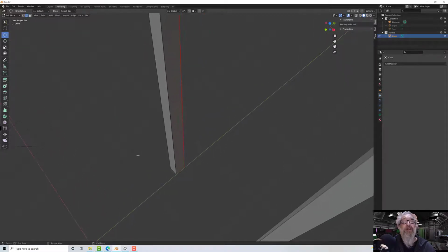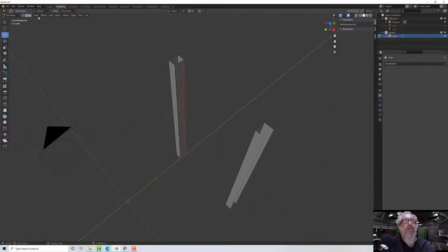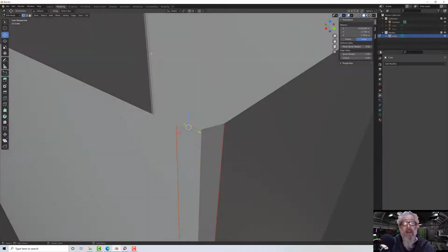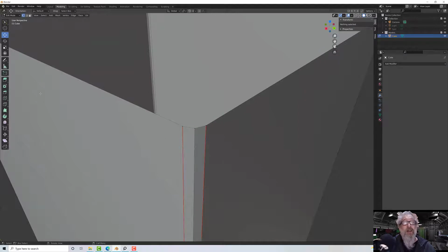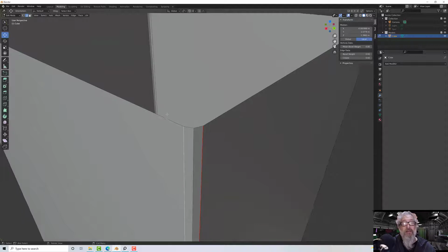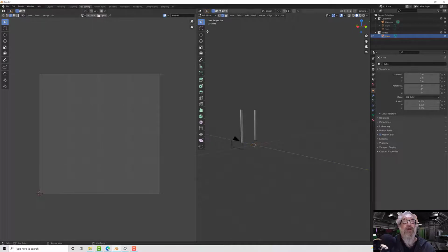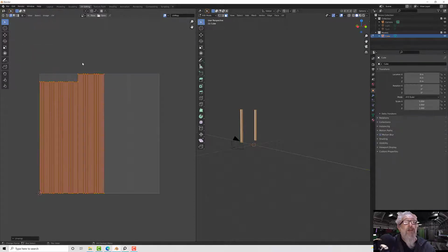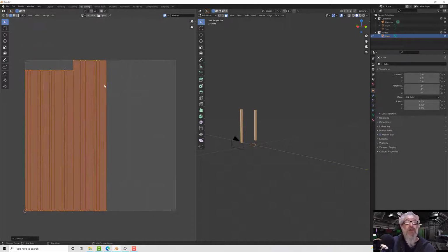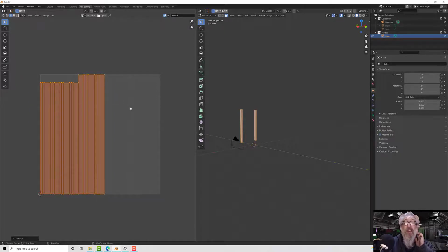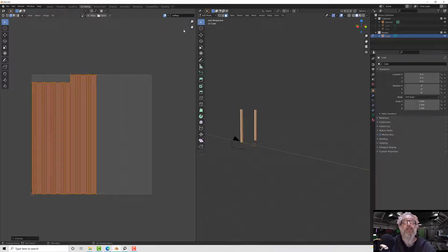Let's make sure that seam hasn't split into multiples. So it has. Okay, so I only need one of those as a seam, so I'm going to select that one, right click and clear seam. There we go. Now we can go back to our UV editing room, select A and A in the 2D view, and right click and unwrap, or U and unwrap, whichever works best for you. Okay, so that's those.